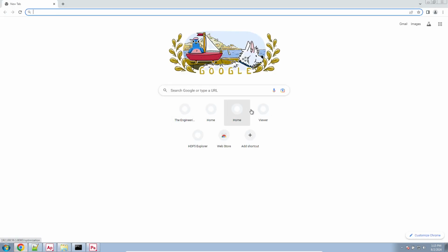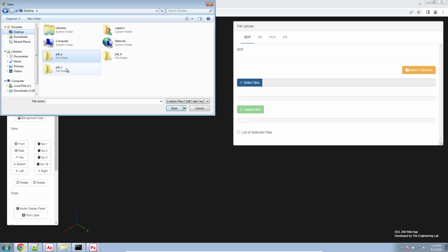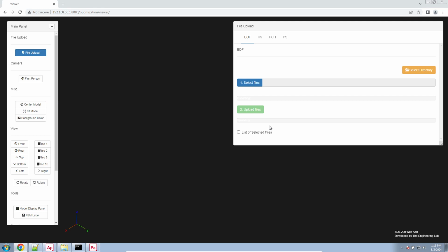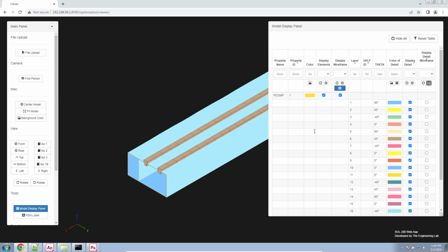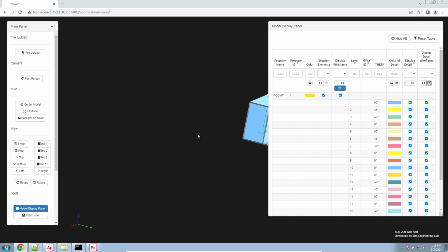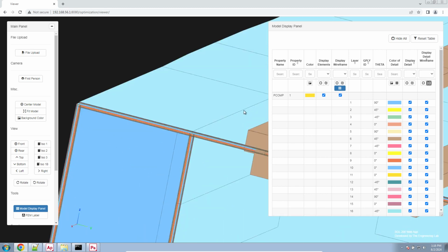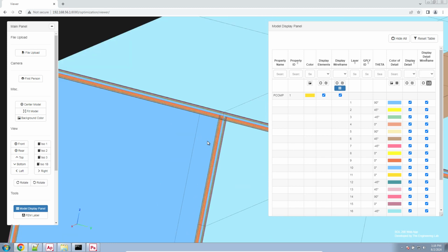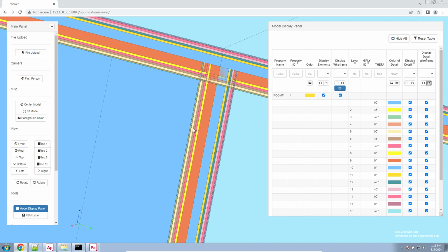Here, I'm going to be using a different tool called the Viewer Web App. One good thing about the Viewer Web App is that it lets you look at your beam cross-section and the layers of your composites. So let's go ahead and import that bulk data file, and turn on all the layers. So now if we zoom in very carefully, these are what my layers, what my plies and my core look like for the pcomp entry.